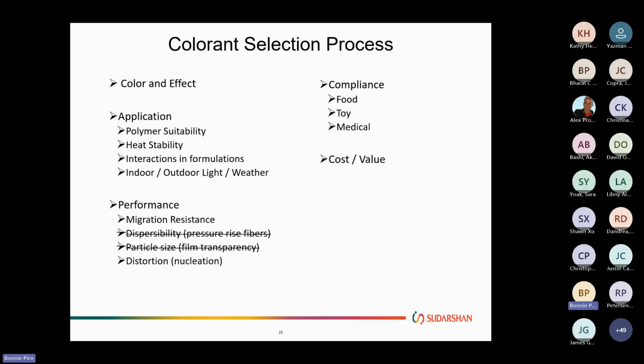From a performance perspective, it's not a particle, so there isn't a dispersibility except for that solubility part of it. Particle size, again, we get that transparency through the dissolution. And of course, compliance comes in every aspect when it comes to plastics, to make sure that your formulation meets the required compliance areas, depending on where that article will actually go. Cost value, I also talked about earlier: because these are used in such low amounts, there's a good value in using solvent dyes.